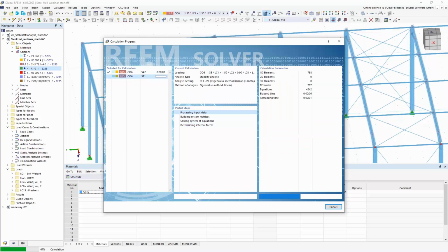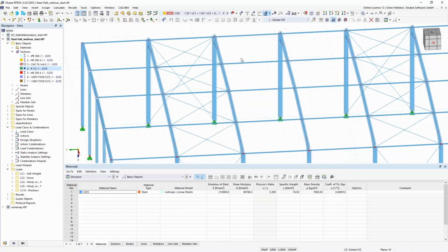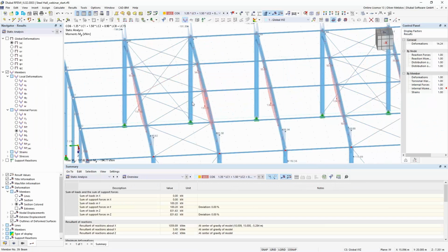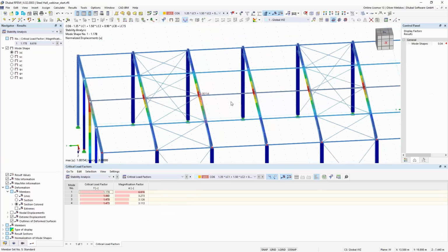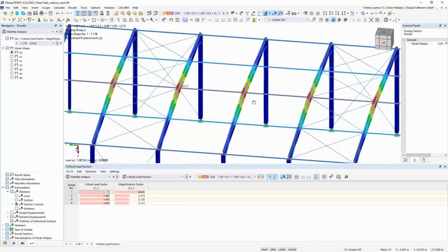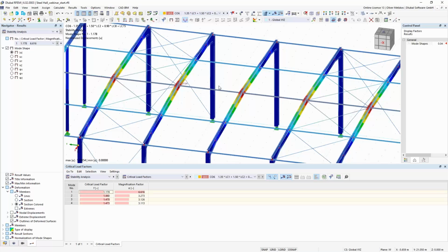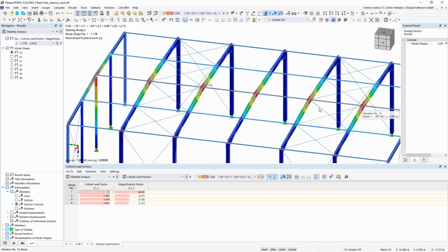So in this load combination number 6, before it was this lateral torsional buckling between the fixation of the bracing. But now we have a lower stiffness, and now it's not stiff enough to prevent this flexural buckling of all the frames. So now we have a lateral torsional buckling mode shape with critical load factor 1.1. So the first one is now the most critical one with this lateral torsional buckling mode shapes, not between the bracing fixation, because the stiffness is too low now. So we will have this global lateral torsional buckling here.